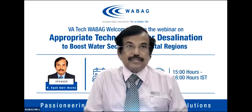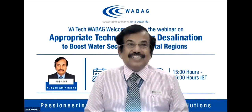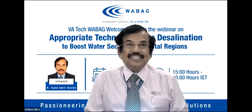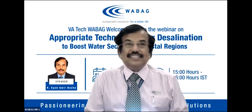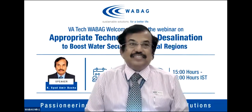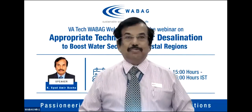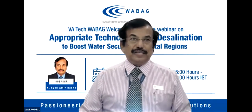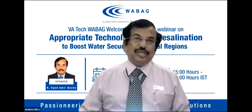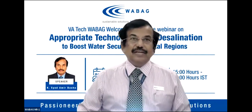Okay, one more last question from Mohammed Farooq Khan. How are the pre-treatment equipment, including DMF, piping, valves, etc., protected from seawater? Is a rubber lining or duplex SS the only solution available? Both are being used in practice, but super duplex stainless steel, when it is used, you can be rest assured that you need not open the valve for another 4 or 5 years.